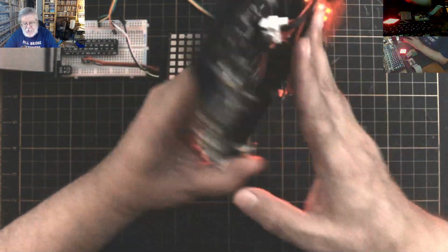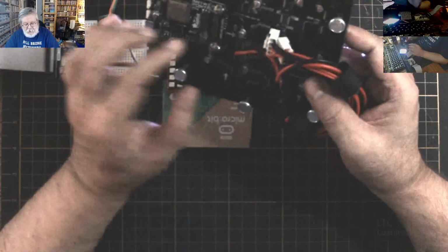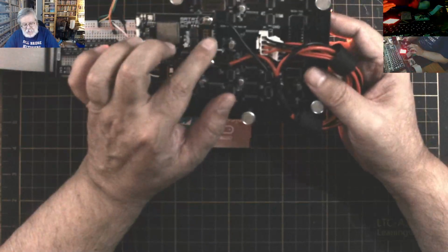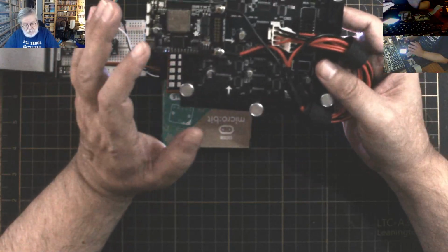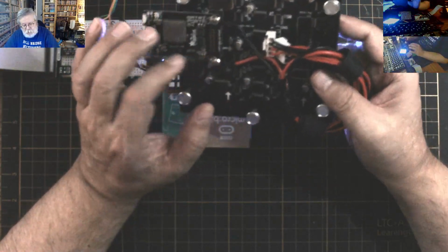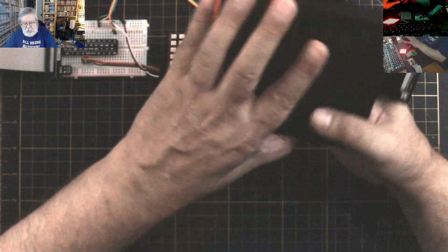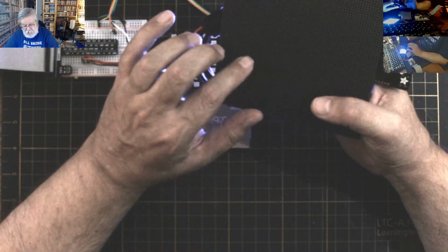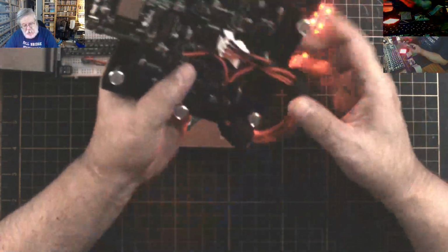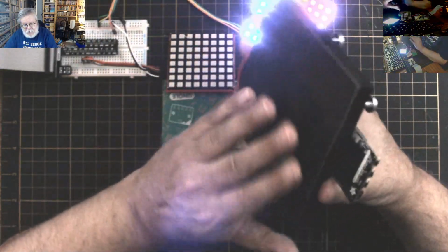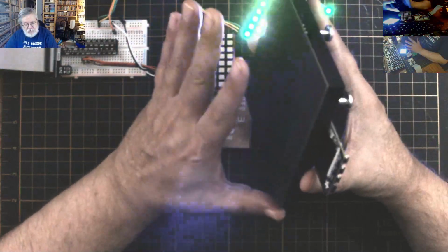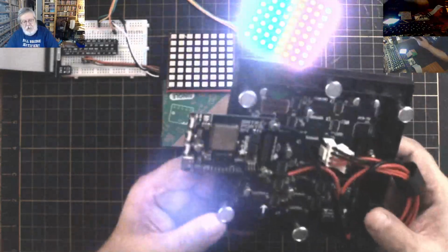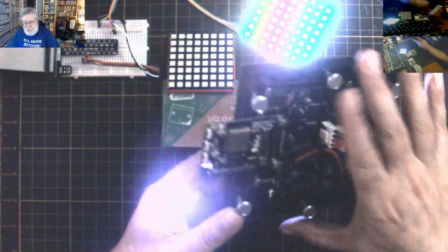And it uses what they call the Hub75 interface. So some of these pins in here control power and stuff like that. Others control what they call data pin A, B, C, D, and sometimes E. In this case, this does have an E, right? And it divides the panel into sections, and when you send signals down the A, B, C, D, E lines, things light up. And there's code for this too.